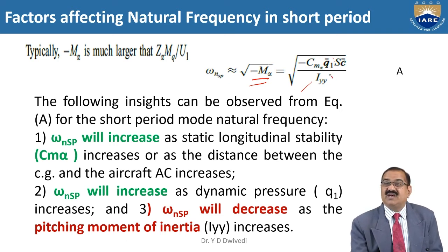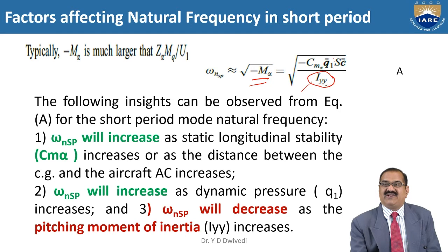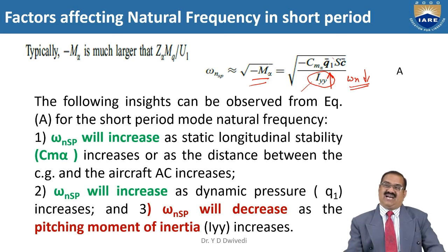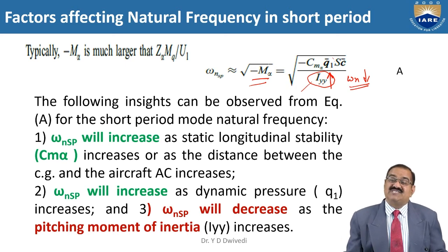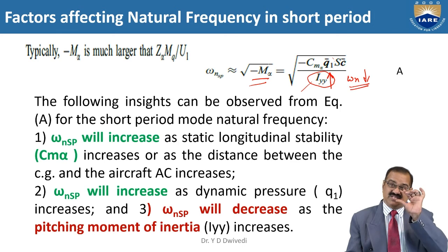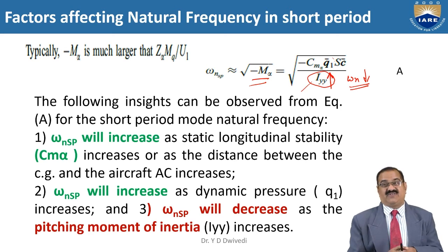Iyy is the pitching moment of inertia. If you increase it, omega n will decrease. So if you have more moment of inertia, your natural frequency will decrease. You have to remember this equation, and you should apply it in the real scenario of the aircraft.